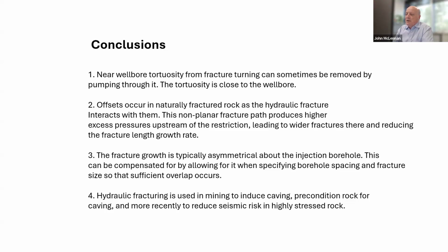UMass would like you to comment a little bit on what causes the tortuosity. Is it related to stress concentration? Are there other factors that you might advise us on? I think it's caused by the fracture encountering different structures or features in the rock mass, which can be natural fractures and quite often is for the macro tortuosity effects.